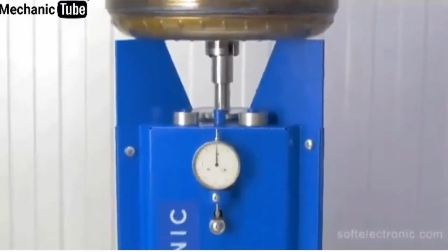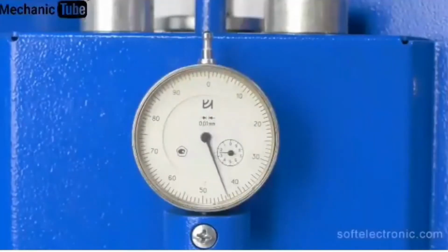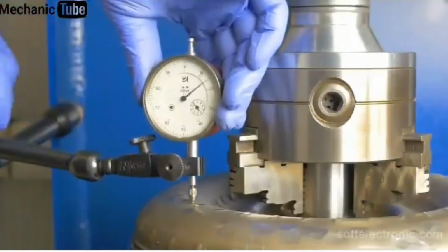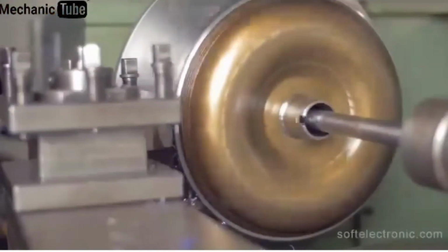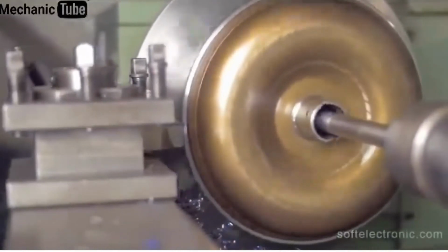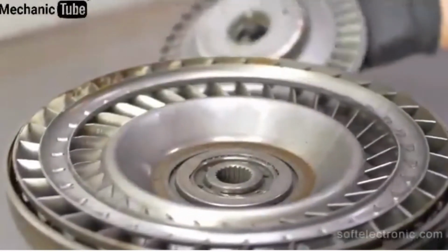Depending on the model, tension and gaps are measured. This can give an initial idea of how worn out the components are. It is checked whether there is deviation in the balance and the axis of rotation. This is followed by a careful separation of the torque converter housings and cleaning of the welding areas. The disassembly of the torque converter continues.